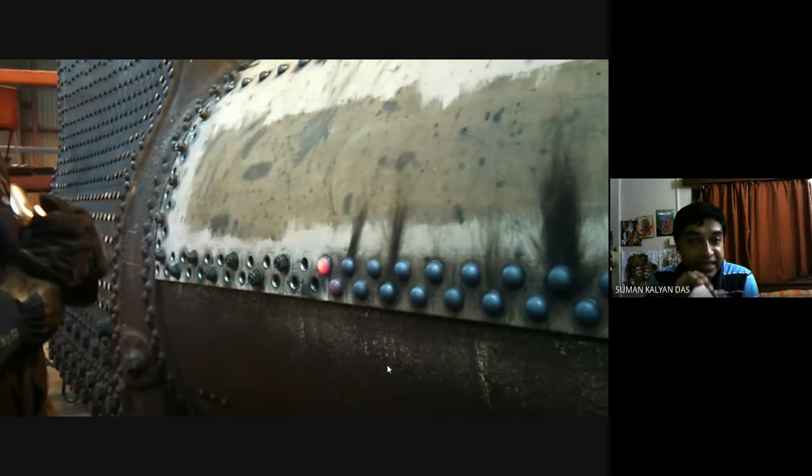So you need to temporarily hold this until you make the rivet. So what is that temporary thing? You are using that nut and bolt system to hold the two edges together temporarily. As he is making the rivets from one side, he keeps unscrewing the bolted joints from the other side. That's how he is gradually proceeding from the right side to the left side.